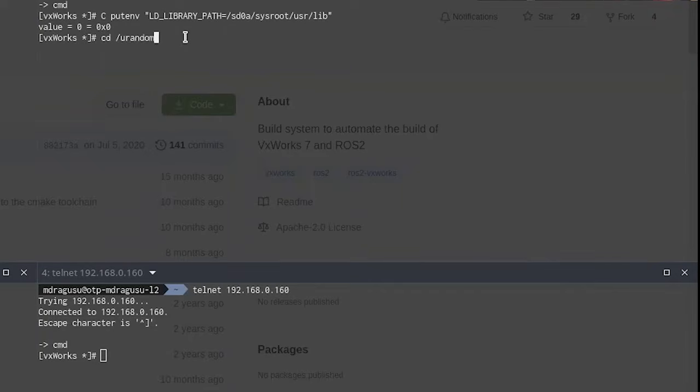By the way, when you're using VxWorks, if you want to delete something, it's Control H, right? It's not backspace, it's not delete, it's Control H. That's one fun thing to know. And the other one is, if you want to run the previous command, it's not up, it's Escape K. Those are the two weird things that you need to know. Secrets from your adventures in VxWorks.